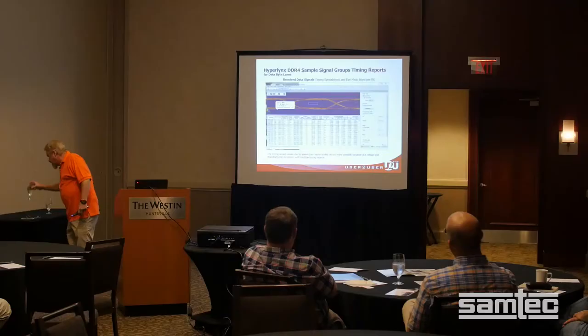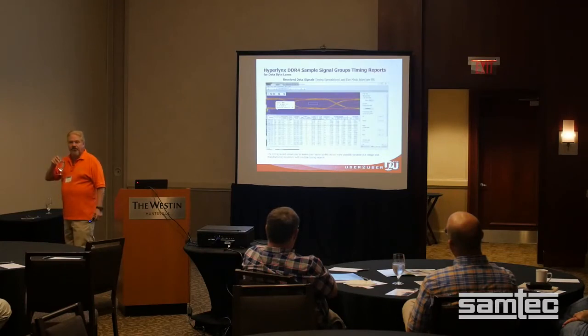So on the timing models for DDR simulation, do you typically use the built-in HyperLynx timing model for the DRAM? Yeah. Because I wouldn't imagine you would need to build one. Yeah, it's just the JEDEC spec. Now, what you do is they have the standard controller one. You go through and change what you need to change. Because since you've used it, you know there's a lot of numbers in there. So change that part. Now, I can't tell you which ones they are. That depends on what the manufacturer is and see what they have. And that's not uncommon. For the first year or two they make them, they push it pretty hard, so some of them they can't make the specs on.